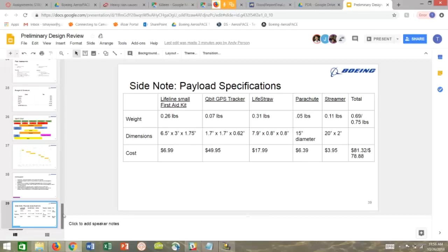It's as simple as it can be, probably very weight efficient, which allows you to maximize your payload. I'm a little confused why you chose the 2 vertical tails rather than maybe just a V-tail configuration, which I believe is more weight efficient. And one thing that I didn't gather is whether the mission is planned to be carried out at night, and do you have an infrared capability in your camera?